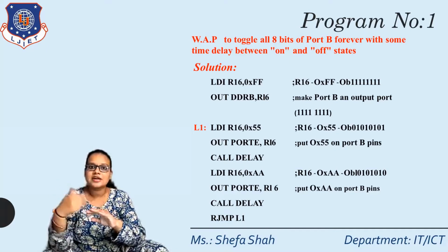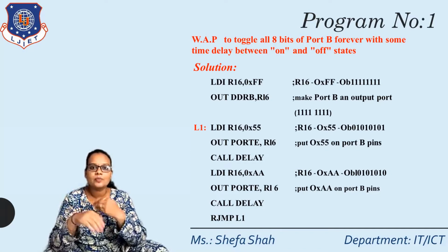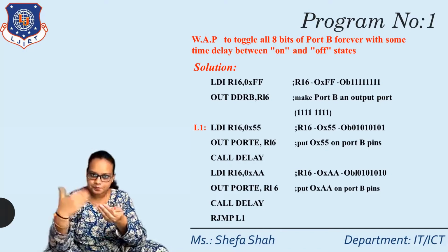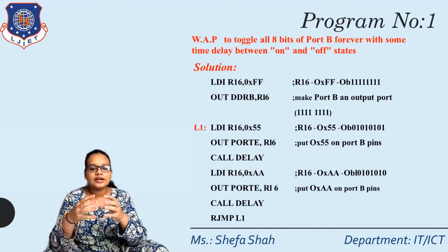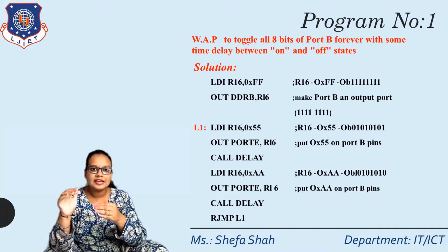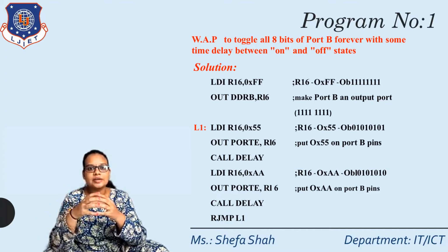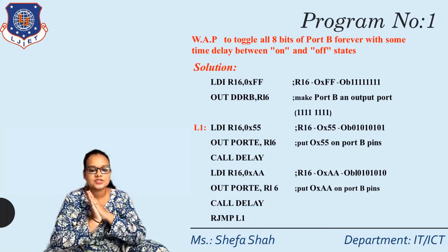Right, we will study in detail how to make the delay loop after the 2 sessions. So now call delay. We have called the delay of some seconds. After calling the delay, there will be a delay loop, and in that there will be instructions for that particular time interval, how much delay we need to calculate. The last instruction in that particular subroutine will be a return, so it will return to the next instruction.